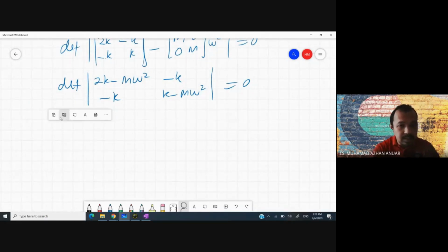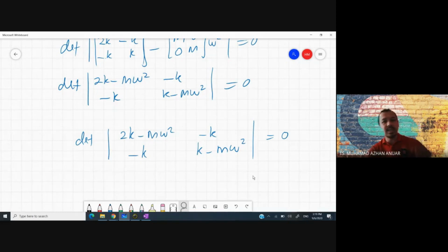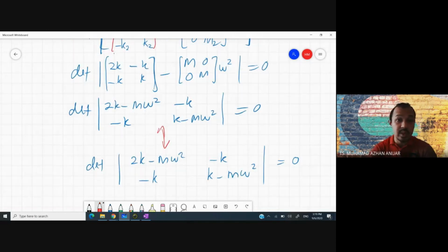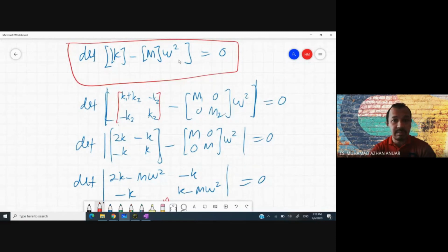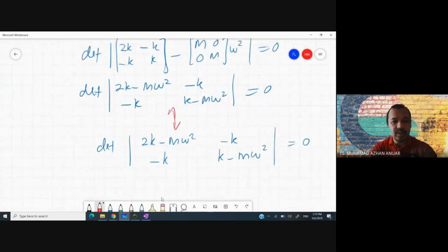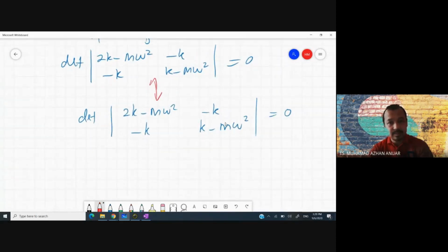You can see that these two are a bit similar, but we reduce a bit on the steps by using our equation here in the red box. You use this equation, use the matrix representation, and straight away you get this representation. And then after this you follow the same steps, do the determinants, and represent omega to the power of 4 as omega to the power of 2 with lambda, and so on, then substitute and get the omega n, get the response.